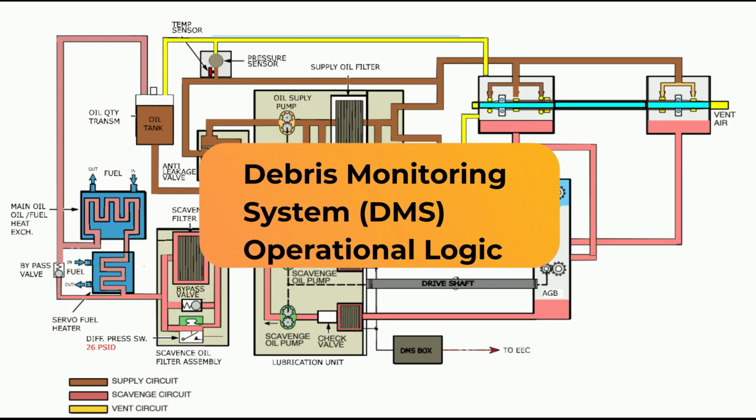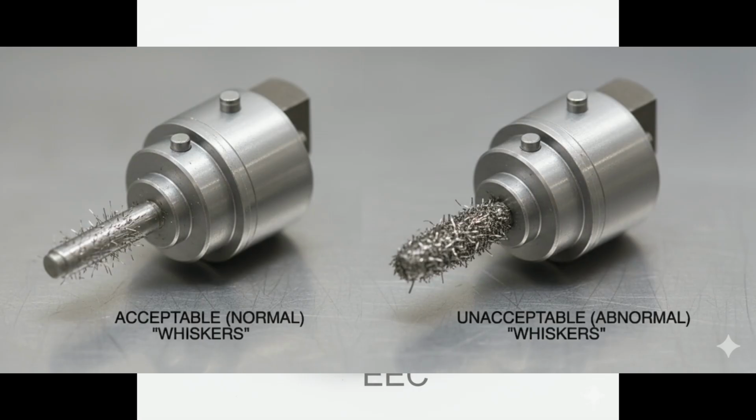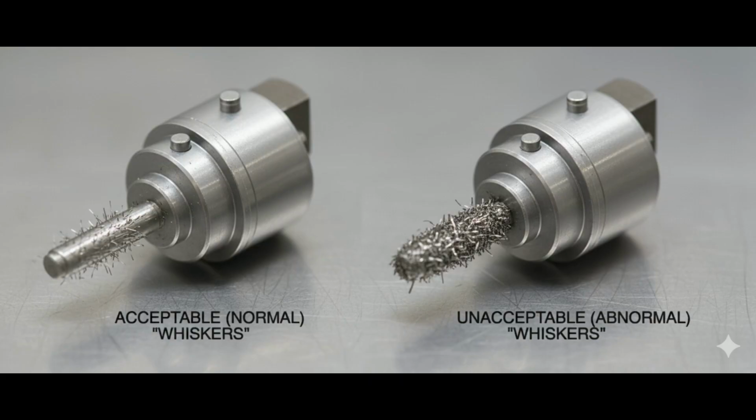Debris monitoring system operational logic. The operational principle of the debris monitoring system can be explained as follows. Pure engine oil is non-conductive, meaning it has a very high electrical resistance. However, when metallic particles contaminate the oil, these particles create a conductive path for electricity. Ferrous particles are attracted by the 2 magnetic receivers, causing the measured resistance values to become significant for system evaluation.